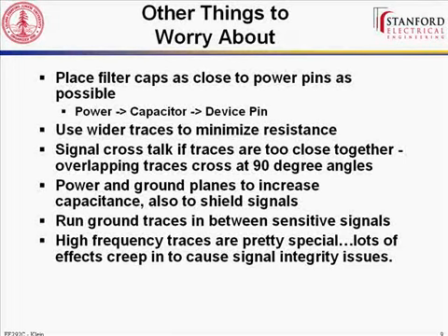So the question is, are you only worried about crosstalk with traces that are high current? So high current will make more crosstalk because the crosstalk is a function of current. However, you're not worried about them just with high current. If you have very sensitive signals, or if you have anything high speed, you have to worry about crosstalk. Because remember that when you transition from a logic low to a logic high, you're transitioning from 0 volts to 5 volts. So there is some impulsive current flow going down that line. So just because it's not a high current that you may traditionally think of like a power rail, doesn't mean that there's not high current noise going through there that can cross-couple.